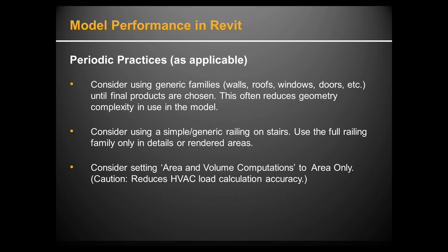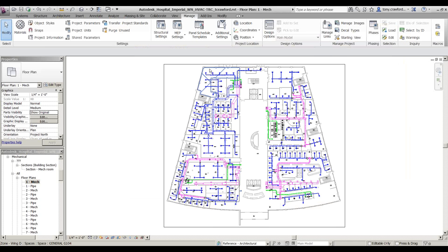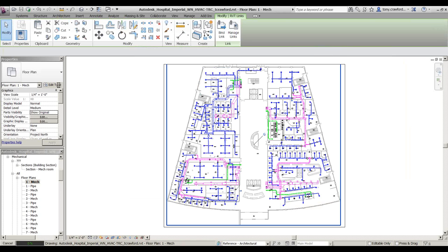Oh, I had one other comment on there. If you're using the different families, by all means, you can draw a 2D family that shows up in 3D by using model lines that'll fulfill any requirements that you need. So keep that in mind. If you need a chair and you need to see where the place is, you can actually use model lines when you build that family so it shows up in 3D. There's no problem with that. It'll still print the same. It'll look the same. And by all means, I encourage a ton of people to go out and do that.